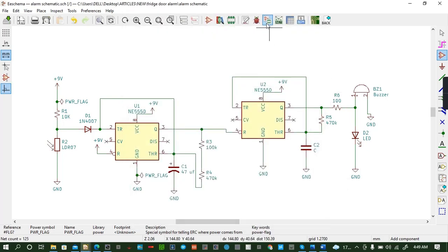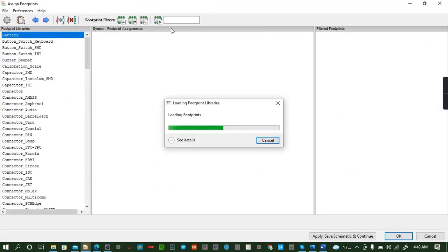For power it's correct. You go to the next bit, which is addition of footprints to the system. So you want to add some footprints to our schematic. Before we proceed to the next bit, let it load. It's taking some time. Footprints will give our schematic 3D symbols. So it's very important to add footprints anytime you're doing a PCB design before you proceed to PCB layout. Okay, it's taking some time, but it's about to be done. So you have to wait for it to do it.